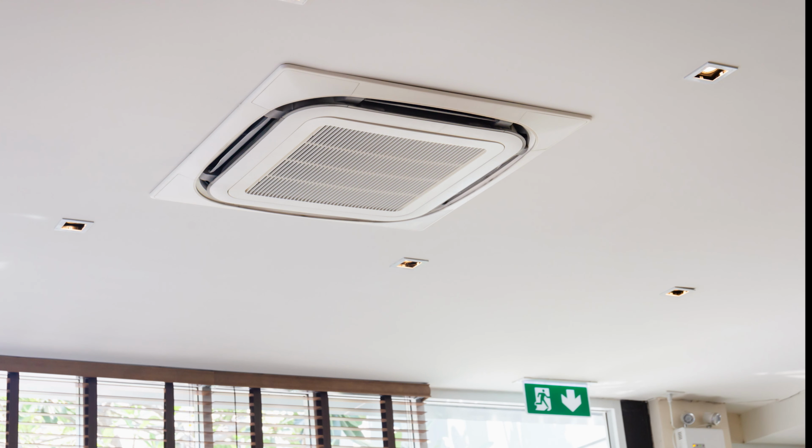The indoor units have a number of different styles, but they all ultimately have a heat exchanger and a fan to blow the warm air into the room. One practical advantage of air-to-air heat pumps over radiator heating systems is that the indoor units are most often ceiling mounted, which frees up the wall space at ground level. This is particularly useful in shops where wall space is usually at a premium.